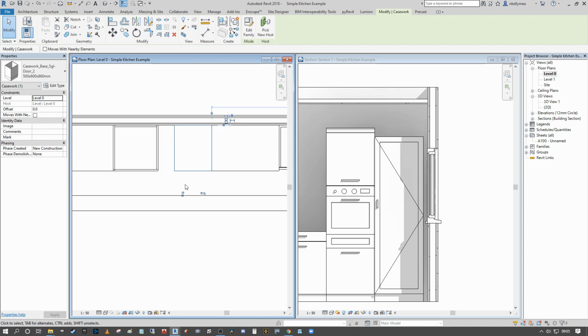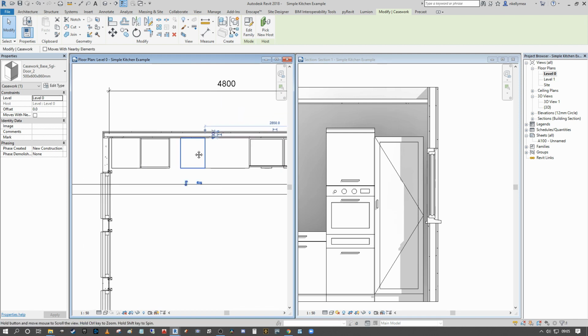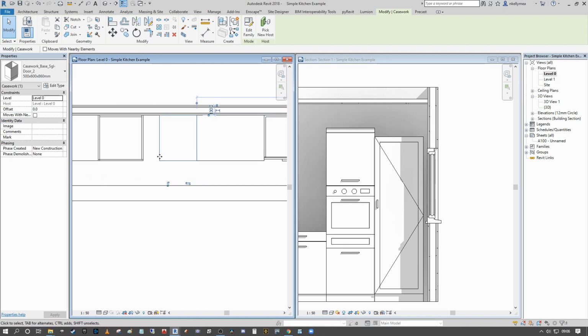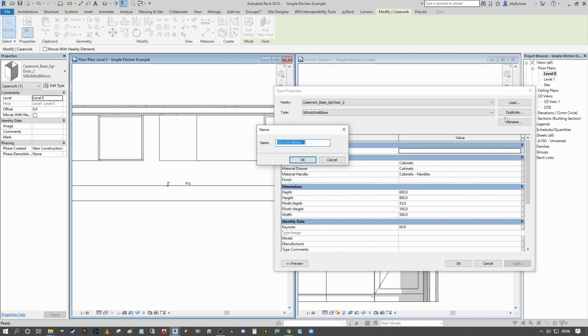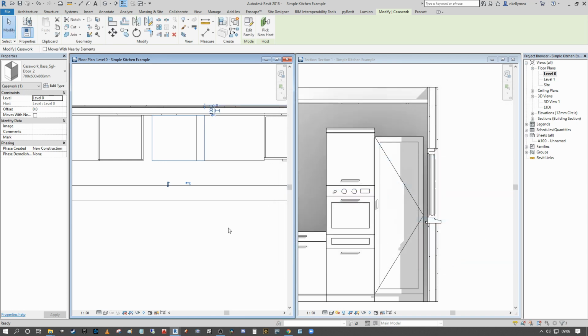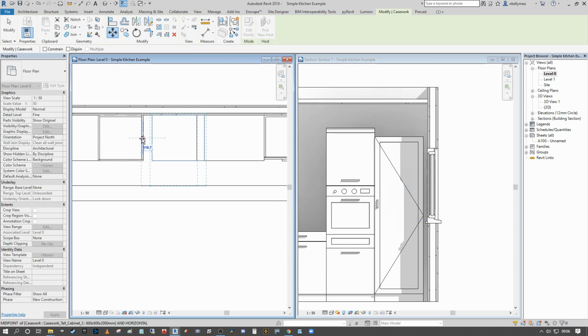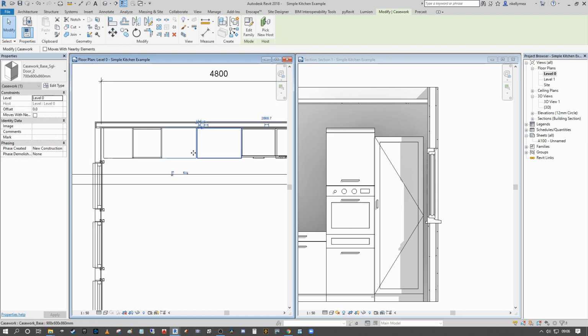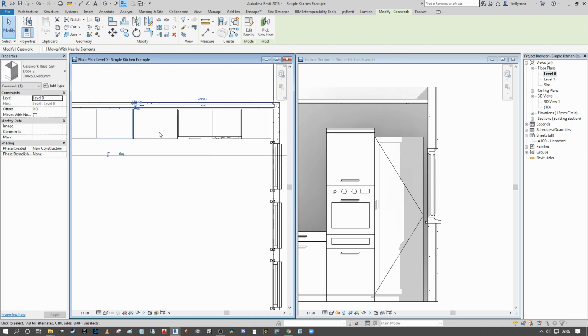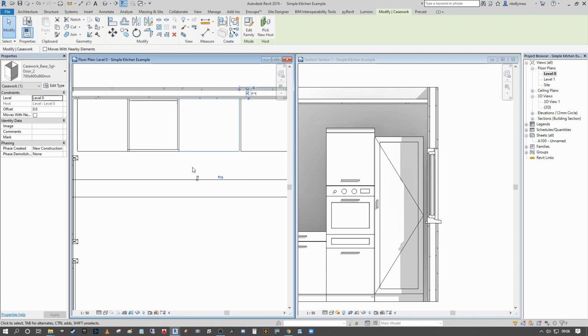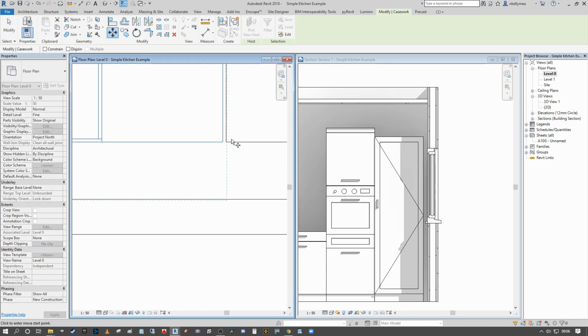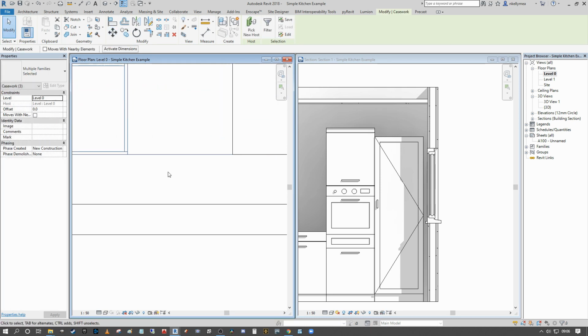And we have a 500mm cabinet here. So again, if we wish, we can change this and press edit type. I'm going to duplicate and I'm going to set that to 700. Press OK. And on our width, we're going to set our 700mm to our width there. Press OK. And then we merely need to move that 100mm approximately. So we have a little bit more of a discrepancy on this side than we did on the other side, but that's no problem because we can select our entire assembly where you can move it across.